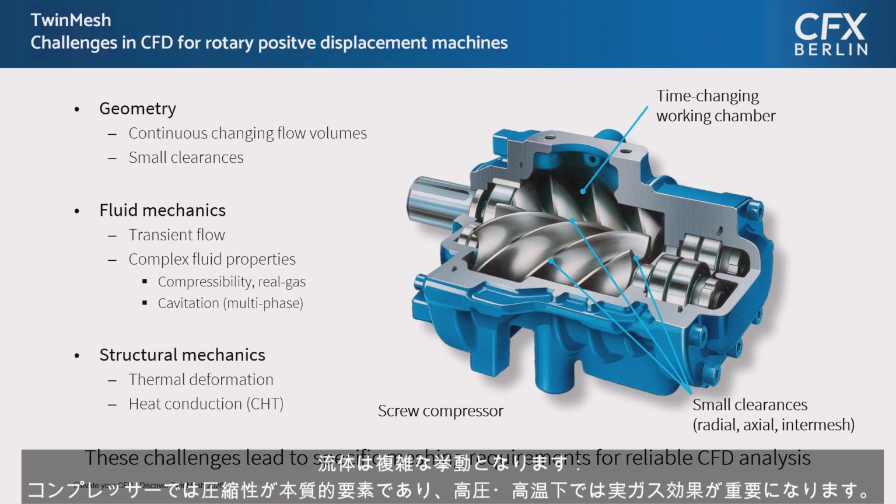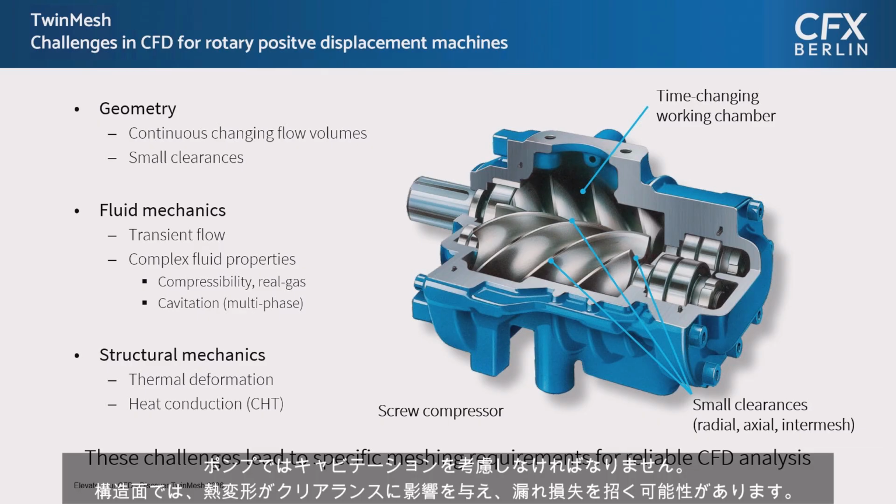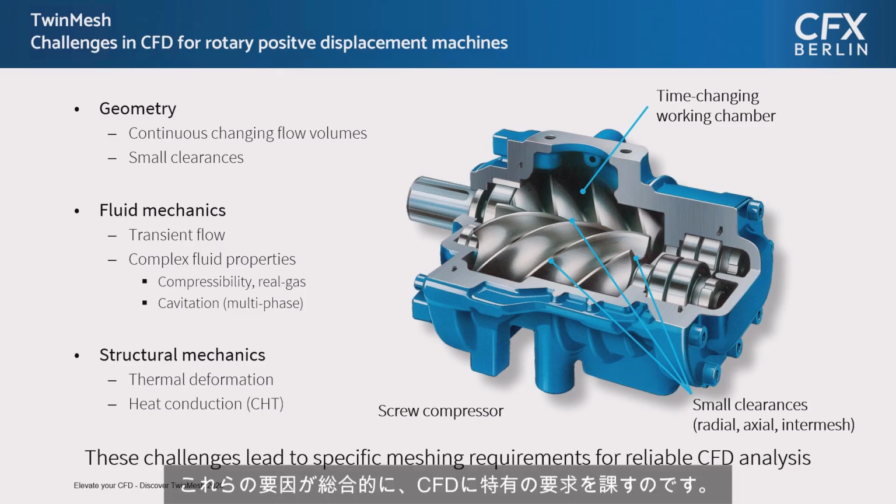The fluid behavior can be very complex. In compressors, compressibility is essential, and with high pressure and temperature, real gas effects become important. In pumps, cavitation must be considered. On the structural side, thermal deformation affects clearances, which could lead to leakage losses. Altogether, these factors impose specific requirements on the CFD.